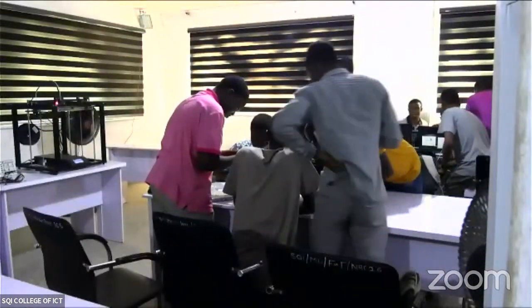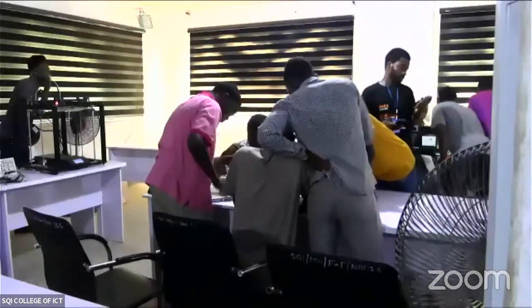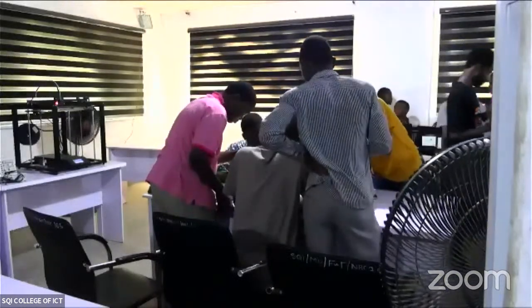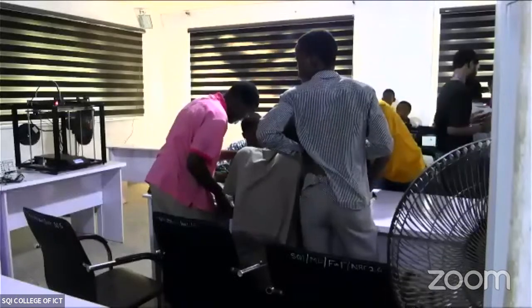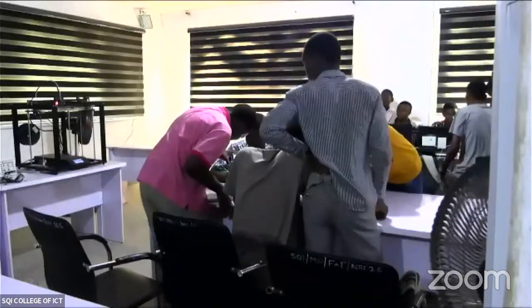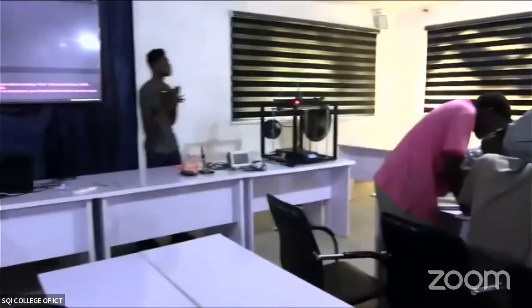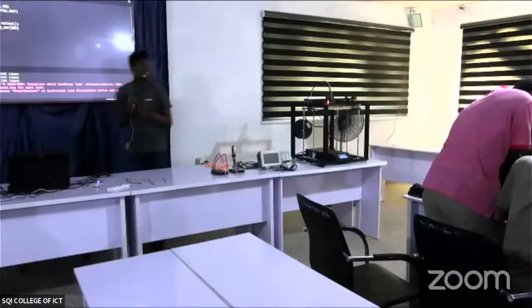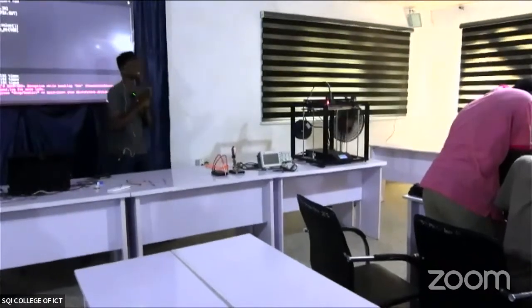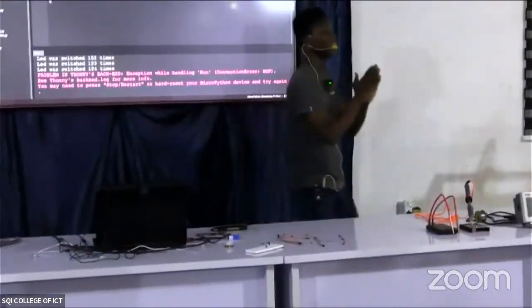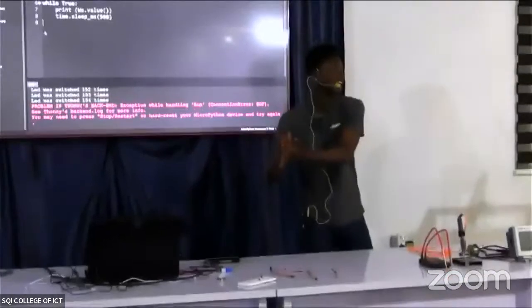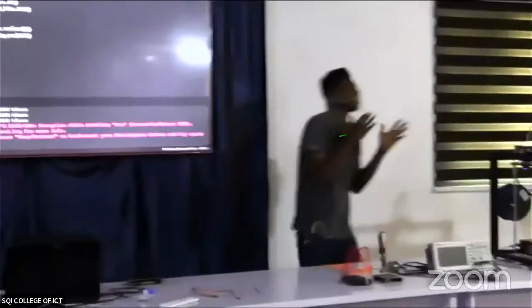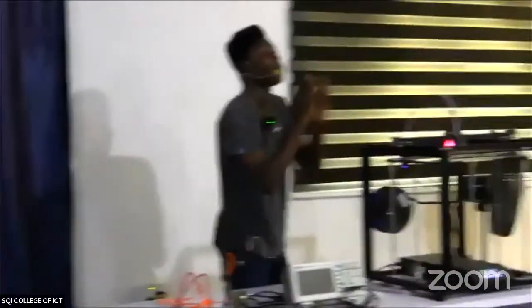Now you guys should remember something in the specifications. I said your Pico cannot handle anything greater than 5.5 volts. Sometimes you'll have to trigger something that deals with 24 volts, 50 volts. This relay module here is what helps you isolate between the 5 volts that your Pico can generate and an external source to power something else. So your relay is like an automatic switch.